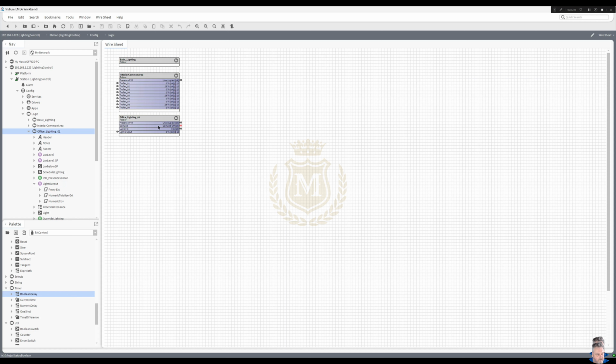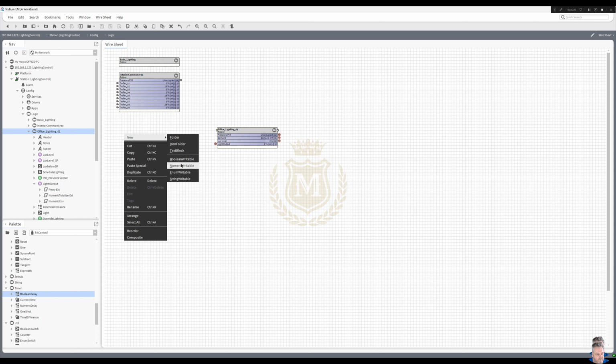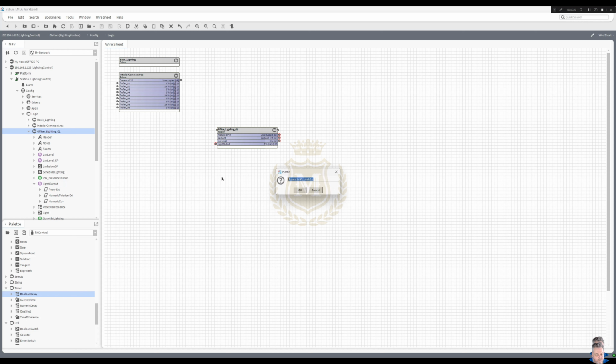Presence PIR. Demand. Lux level. Right. So what we can just do here is numeric writable, and just put in action set to 300. Lux level outside or inside is 300 there.